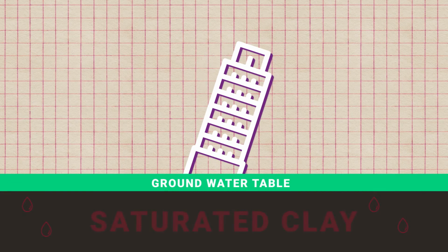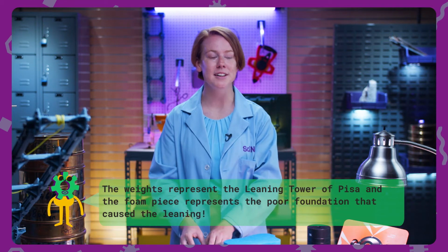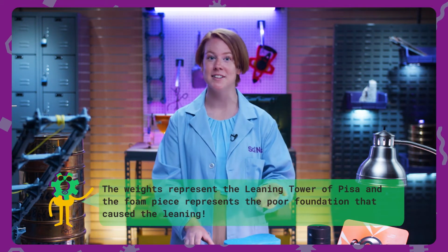The original engineers did not account for the tower being built upon a shallow layer of saturated clay. It's because the site has a high groundwater table that the clay was saturated, and thus a poor location to build on. With a few weights and a foam foundation, we can model the importance of a strong soil profile and see why the Leaning Tower of Pisa got its name.